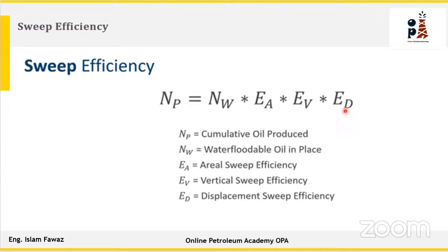But you are working in a reservoir with kilometers, so this is not the ultimate recovery. This is the ultimate recovery factor from the field if we push every barrel of oil from the reservoir. But the reservoir is not homogeneous as you expect. So you have to look at the vertical sweep efficiency if we have a high perm streak in the middle, or the areal sweep efficiency due to compartmentalization, or a baffle, or a very heterogeneous reservoir. All of those metrics you have to look at in order to get the maximum recovery from this field. This is another metric for water flooding.